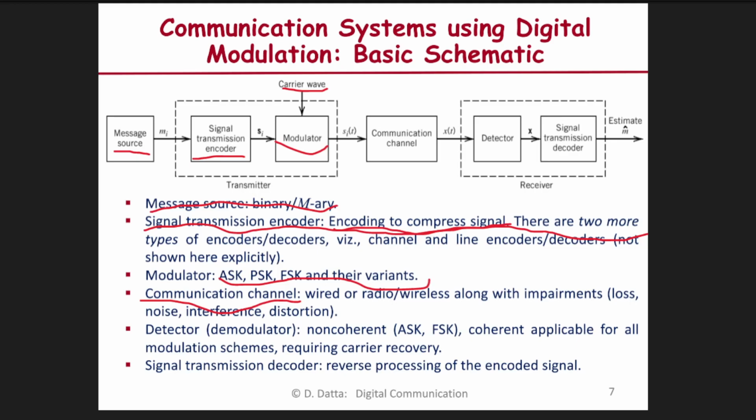Suppose you have got a 1 and 0, like this is 1, right? And then this is 0. Then again 1 and then 0. Now if there is a dispersion, or as I said, distortion, the signal may be like this and then go like this. So you can see now this 0 has got a trace of 1, and if you sample the signal somewhere here, you will get close to 1 and you can make a mistake. So all these things are a part of the communication channel, and we have to fight with them so that our communication system operates successfully. Is that clear?